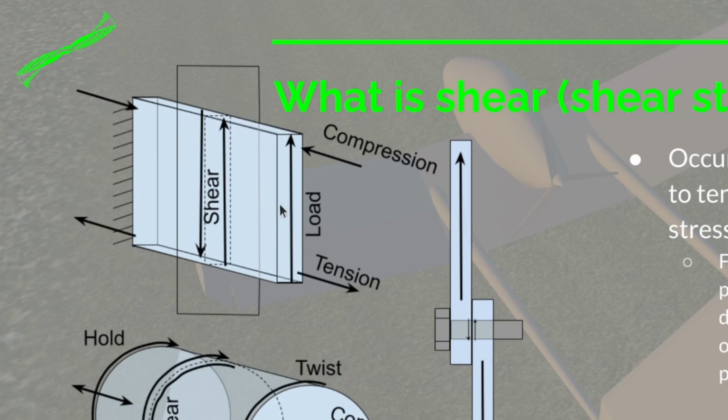In that case, the shear will increase. It'll be zero out at one end, where we have zero lift on the wing, and it'll be added together as we add more and more lift force that's distributed along here until we get to the fuselage, which is going to be carrying all that shear load.